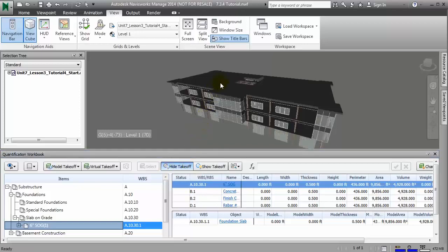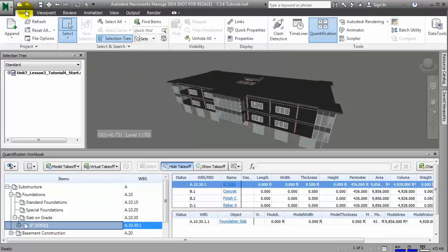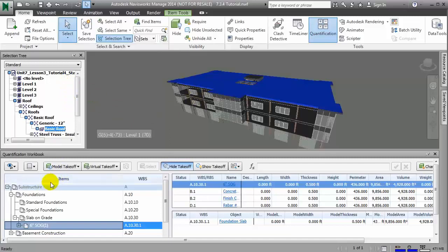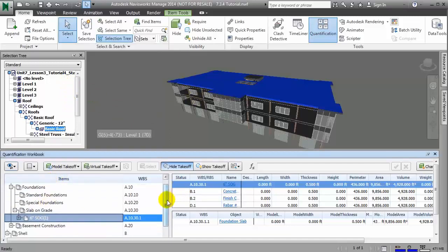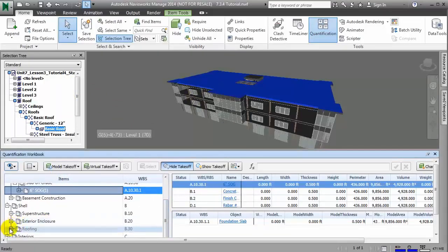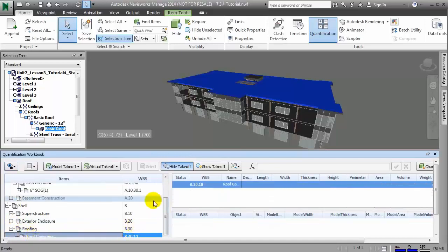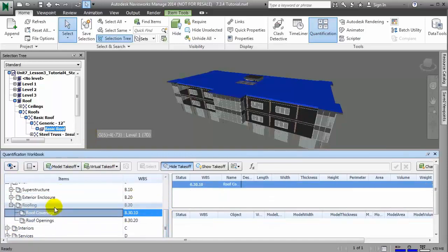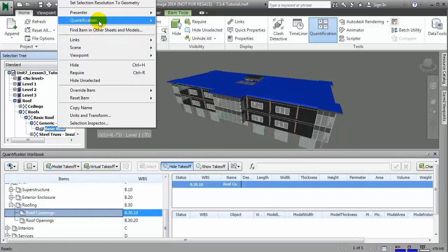On the other hand, destructive takeoff is the opposite, in which we start with a full scene view of all of our elements that have not yet been taken off. For that we use Hide Takeoff Items. And this time we are monitoring what is taken off by viewing which items disappear from view.